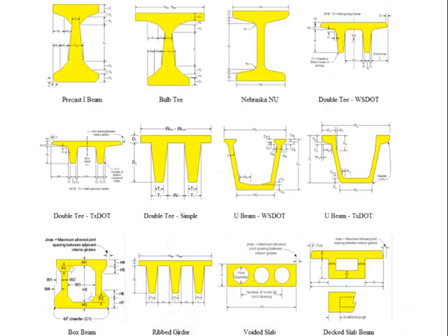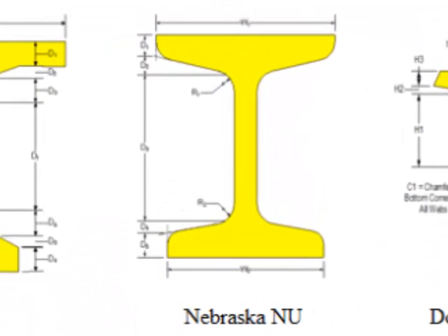At this time, PGSuper has 15 parametric girder types to choose from. 12 of the primary types are shown here. And depending on their type, sections can be spaced adjacently or wide spacing. Some sections allow the input of end blocks and shear key loads, and there's even an I-beam section that can have a tapering depth. But a quick look at our sections here reveals that our section will be based on the Nebraska NU type. Once a girder section is defined, it can be referenced in a PGSuper bridge model and used to design prestressing for a bridge.